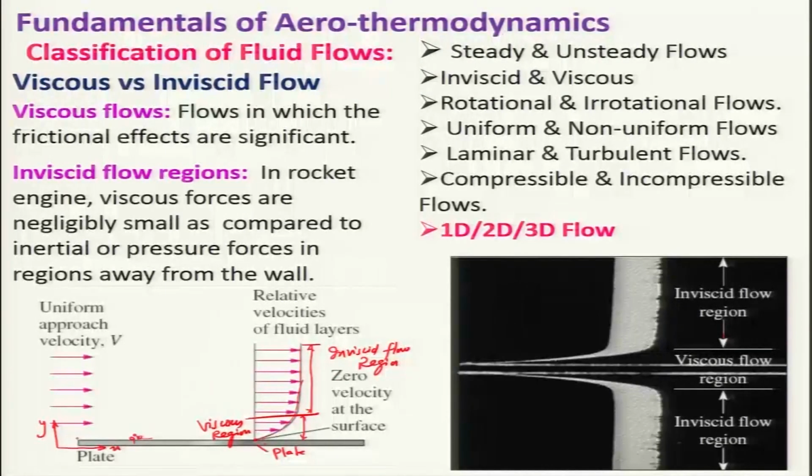If you look at the fluid element, if I consider this as a boundary layer, then the fluid element will be rotating here. In this region there will be rotational flow. But in the inviscid region, the fluid element will remain the same without any rotation. This is basically irrotational flow. In this region, this is basically the irrotational flow region.